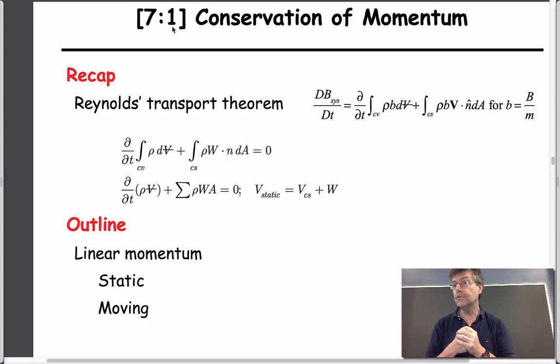And finally, we will do conservation of energy. Conservation of energy also ends up as the Bernoulli equation, but with extra terms to represent the fact that we can add energy into the system by a pump, and we can also calculate energy delivered by the system for energy machines like windmills or hydroelectric plants. We can also use it to calculate for non-ideal viscous flows, not inviscid flows, which Bernoulli really deals with. Those are the three things we do. Conservation of mass we've done. Conservation of momentum we'll do this week. Conservation of energy we'll do next week. And that's the plan. We use Reynolds transport theorem.